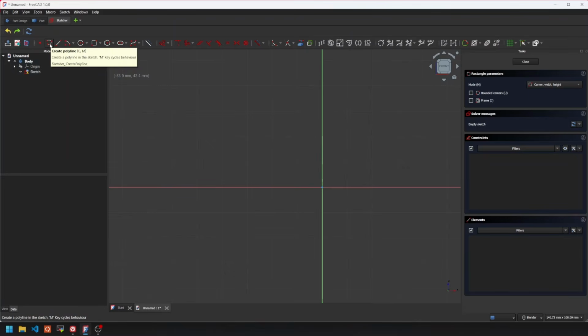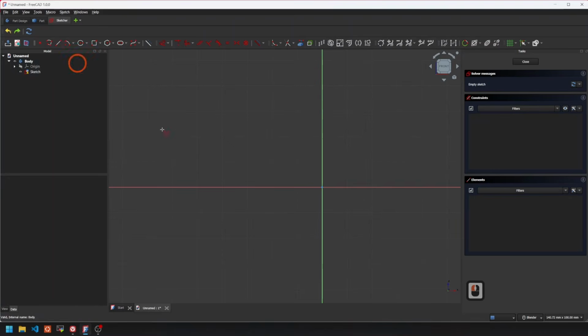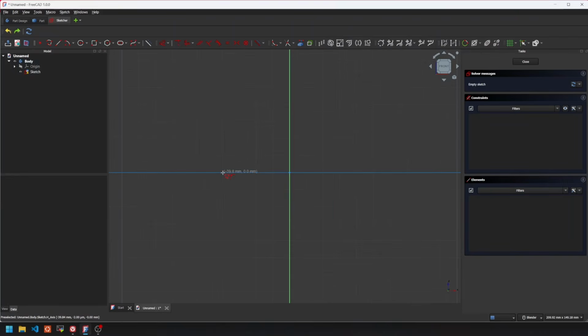And like I said, the mount will have the look of an S. So it's an S-like shape. So I will have to create it on my own. So I will start here and I will draw the first line. And you can see it also shows me the length of the current line. And what it also does, if it's vertical or horizontal, it shows those additional lines. It will automatically add this constraint. This is a constraint for vertical or horizontal lines, which means those lines can't be angled. They can either be horizontal or vertical.